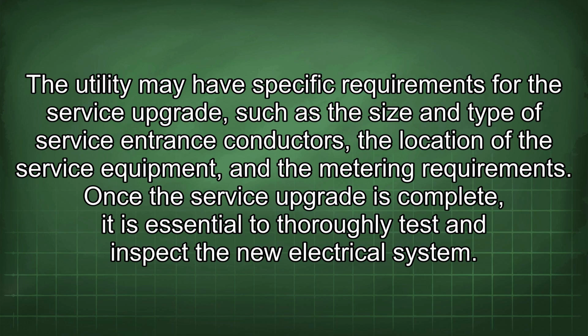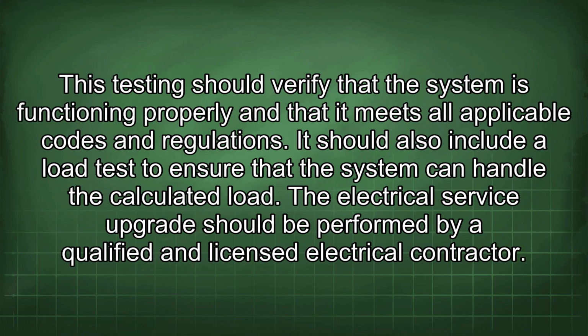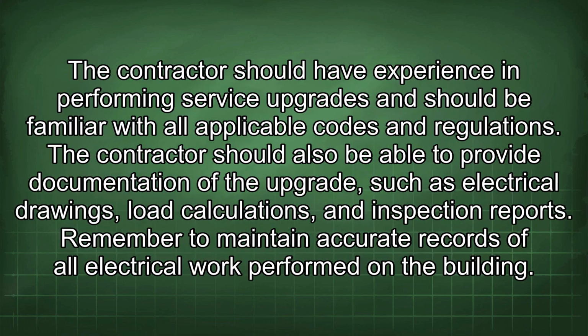Once the service upgrade is complete, it is essential to thoroughly test and inspect the new electrical system. This testing should verify that the system is functioning properly and that it meets all applicable codes and regulations. It should also include a load test to ensure that the system can handle the calculated load. The electrical service upgrade should be performed by a qualified and licensed electrical contractor. The contractor should have experience in performing service upgrades and should be familiar with all applicable codes and regulations.